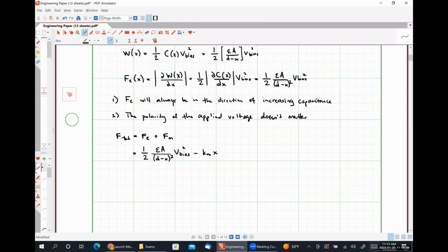But for a lot of applications, like tunable capacitors for RF applications, the pull-in effect is generally something that we want to avoid, because when the plates snap together, the capacitance is no longer tunable. It is just a fixed thing. Actually, it's not even a capacitance anymore because the plates short each other out. Okay, so we are going to analyze the pull-in effect and figure out mathematically when it's going to happen.